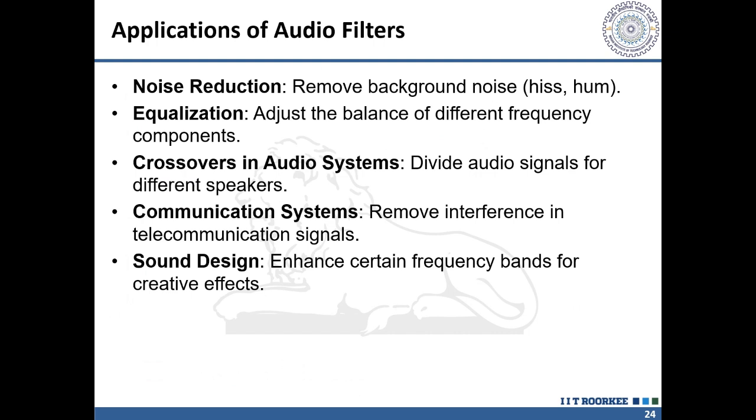So the applications of audio filters, it is used in noise reduction. If there's any noise, any hissing sound, we can use the high pass filter and remove it. And we can use filtering in equalization. We can adjust the balance of different frequency components, and it is used in crossover in audio systems. So imagine a situation where different speakers are aligned in one particular orientation. So we might be needing to remove some frequencies and we need to filter it.